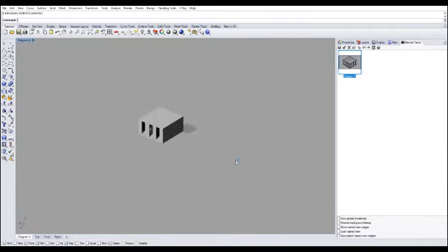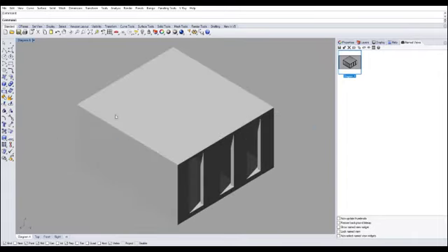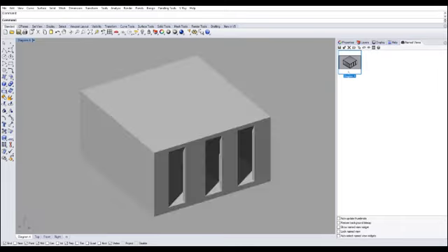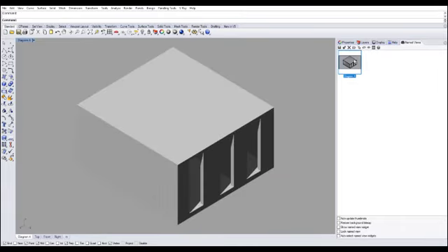Now to go back to that, because we bookmarked it, all you have to do is double click on the area where you bookmarked it in your named views, which is this guy, called diagram A, and it goes right back there. Now after you've done this, please don't start clicking through and do this once more. The idea is you go back here once, when you're ready to render. So yes, now it's finally ready to render. To render, you can click on this button called Render with V-Ray.